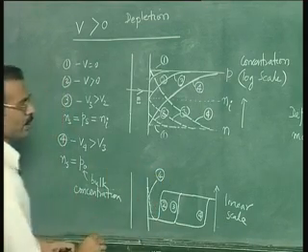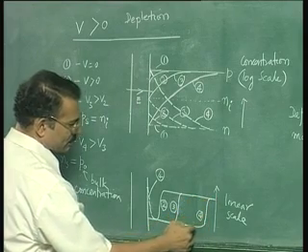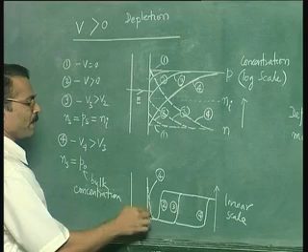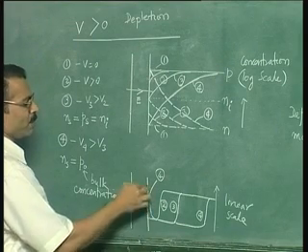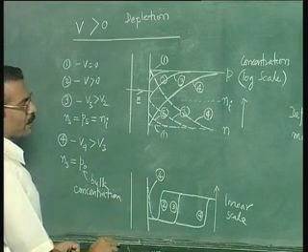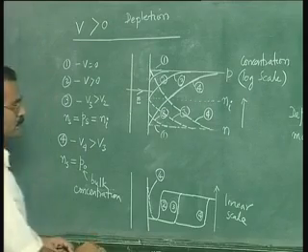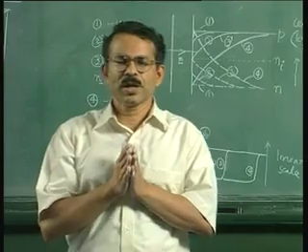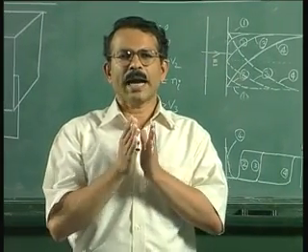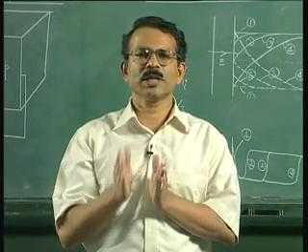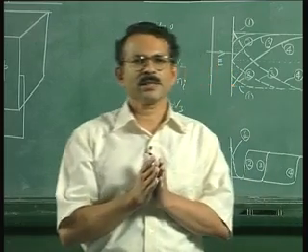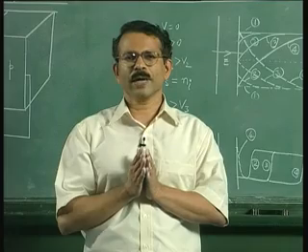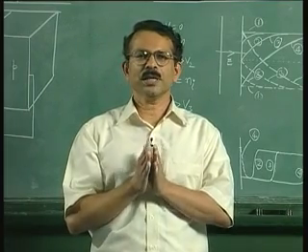For condition 4, the hole concentration is like this, showing depletion of holes, and there is also an electron pile up here, which is now becoming noticeable for condition 4. Therefore, beyond this particular voltage, when the electron concentration at the surface becomes equal to the hole concentration in the bulk, the surface is said to have got inverted. Okay, this is called the inversion region.